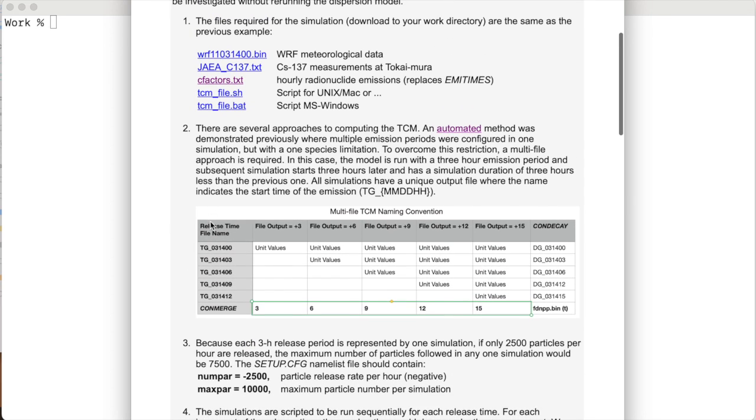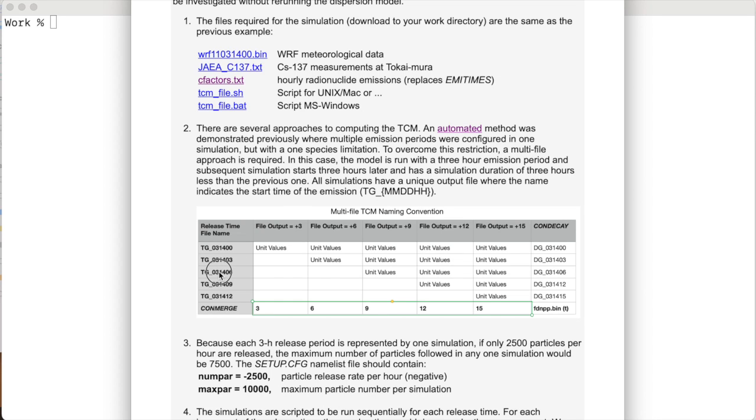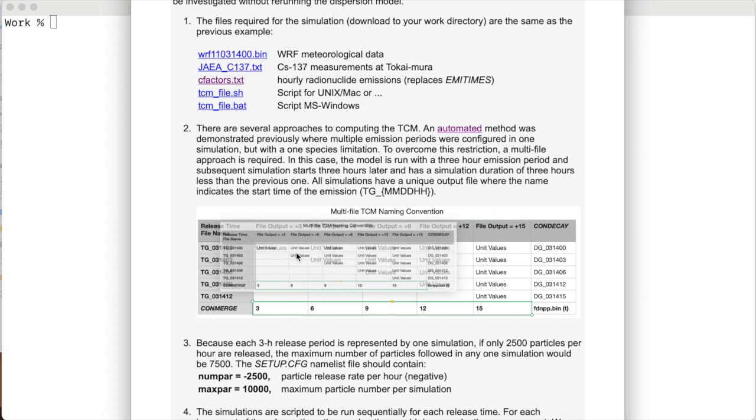The results can still be organized in matrix form, such that we represent each emission time as a row and the concentration grid as a column. Then the column sum over all rows represents the total calculated concentration for all emissions. That is a conventional concentration map, while the row sum represents the contribution of that emission period to each output time.